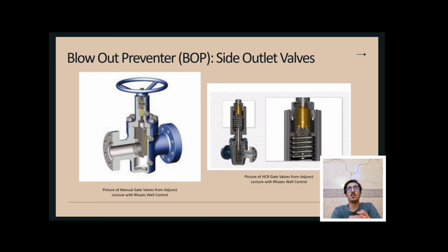Whereas a subsea BOP stack comes with two HCR valves with a fail-safe feature. The manual gate valve is usually located adjacent to the BOP or inside, whereas the HCR is installed downstream of the manual valve. Both exist for the kill line and choke, and must have a rated working pressure that is the same as the ram rated working pressure of the blowout preventer.